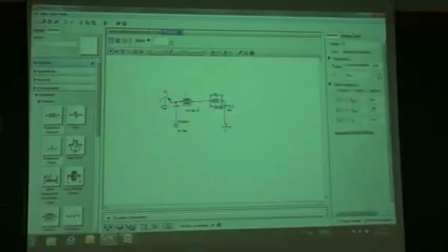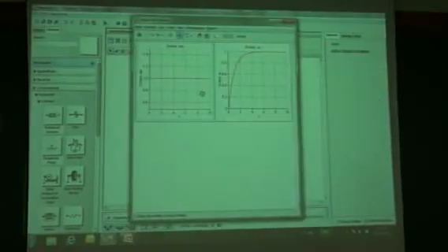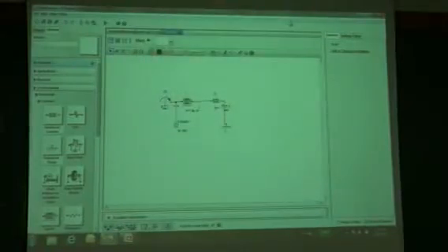Well, way too big. There we go. So now we can see that the damping effect is applying a load to the system as the shaft speeds up, and then it'll come to a balance point at 1 radian per second on here. So just doing this is a very, very quick process to be able to put this type of system together.